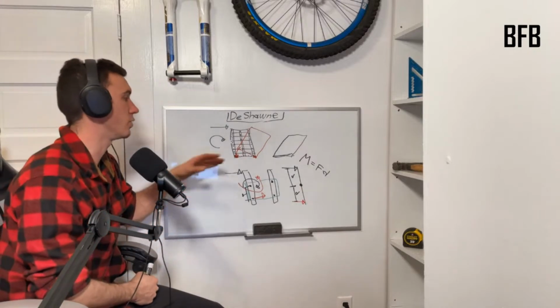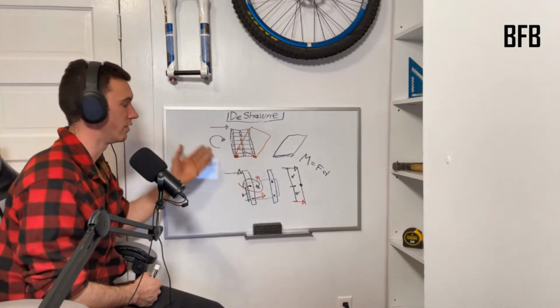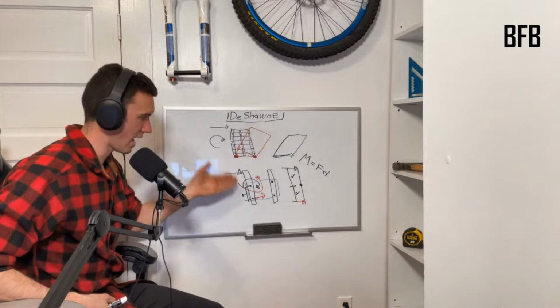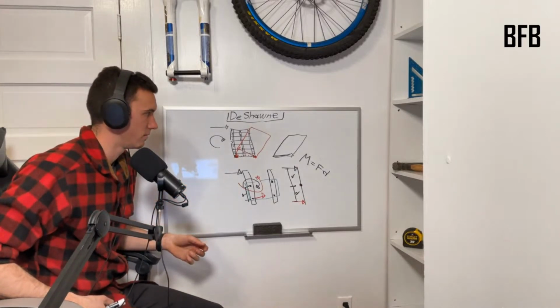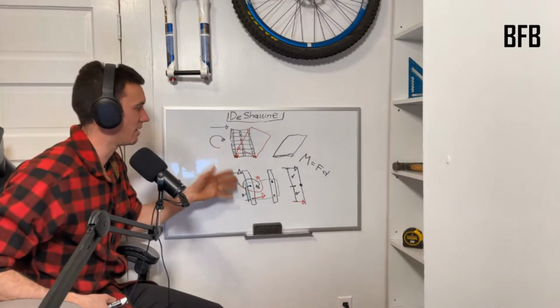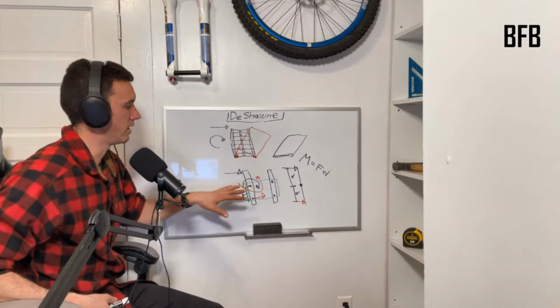And that resistance to twisting is the resistance that the sheet could also give the deck. So that is why planks can still do the same thing the sheets can. Pretty cool, huh? So diaphragm doesn't necessarily mean flat sheet good, but it does mean that it's a system